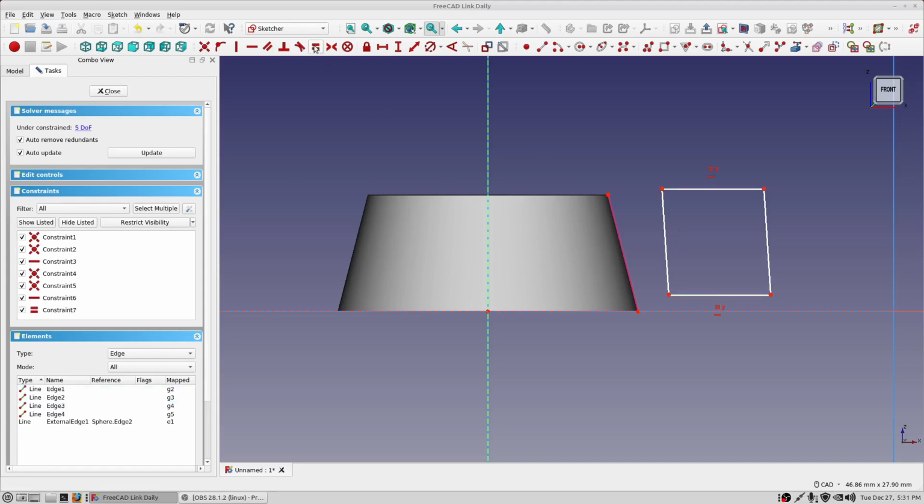So we'll do that. We also want to get this referenced down at the base of this cone or this knob body. We want to click here, and we want to click on the X-axis, and we'll hit that. There we go. That's what we want to do. So the next thing we want to do is go ahead here and click on our reference external geometry line and this, and we want to apply an equal constraint to that.